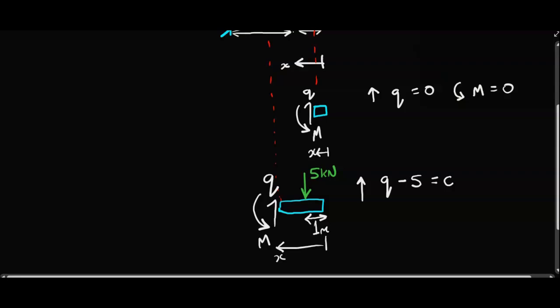And there's no other forces, and they have to equal 0 because, if you remember from the previous video, this is us summing up the forces in a particular direction, in this case the vertically up direction, and we say that they have to equal 0 for static equilibrium because the accelerations are 0. So on the left hand side here, Q minus 5 is us summing up the forces and taking account of the directions with the pluses and minuses, because this is a plus Q, that's a minus 5, and that equals 0. So all of that implies that Q equals 5, or 5 kilonewtons.